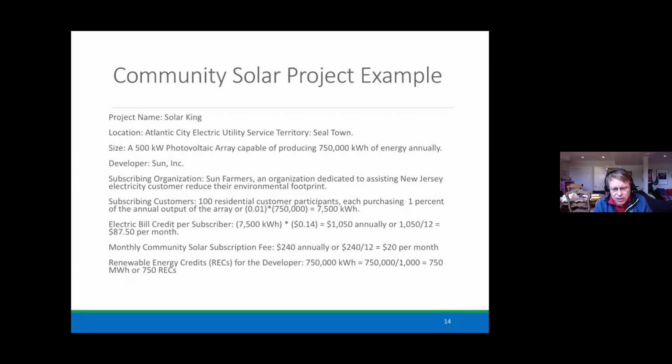And one of the things I would note, which is kind of interesting if you ever have a chance to go there, there are solar calculators for each latitude and longitude, which will give you how many kilowatt hours a typical array can produce. So it's pretty interesting. Obviously, the further south you go, the more kilowatt hours can be produced because the sun shines at a better angle and with more intensity throughout the year. But the calculators allow you to calculate what your solar arrays can produce in a particular location.